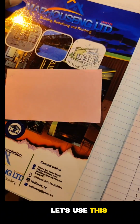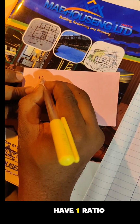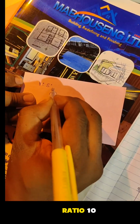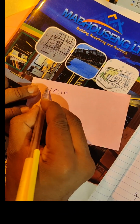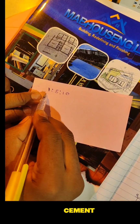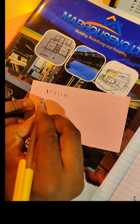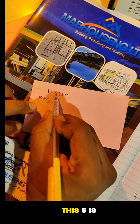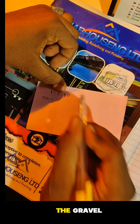Let's use grade 5 now. Grade 5, we have 1:5:10. Okay, let's simplify this. 1 bag of cement is 50 kg. This 5 is fine aggregate, that is the sand, and this 10 is our coarse aggregate, which is the gravel.